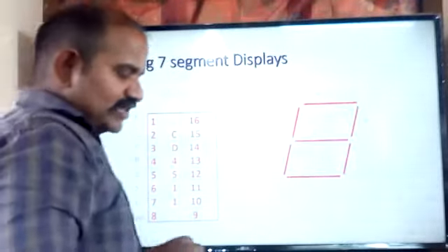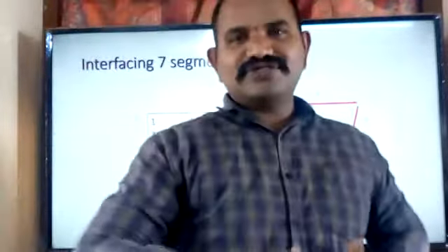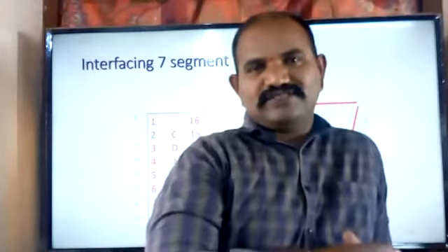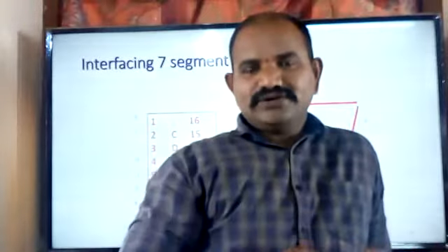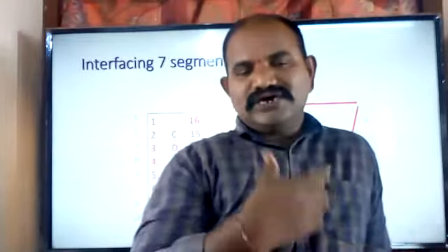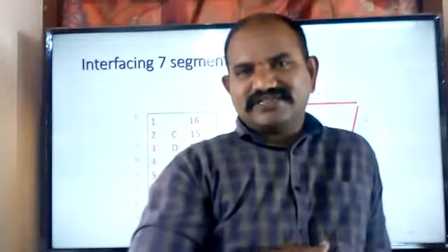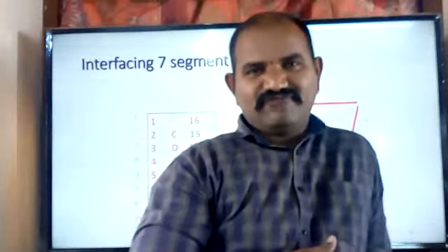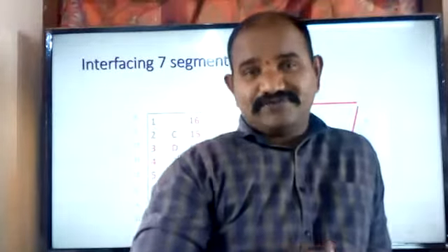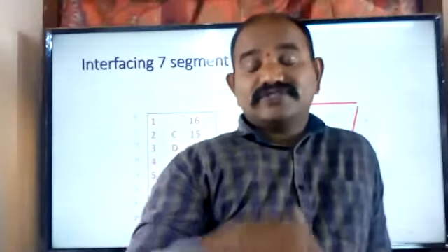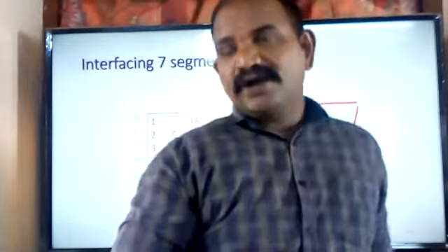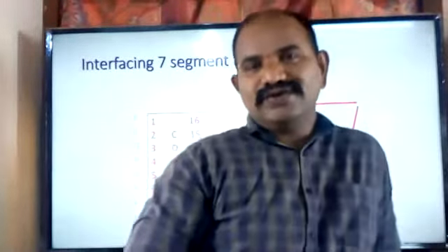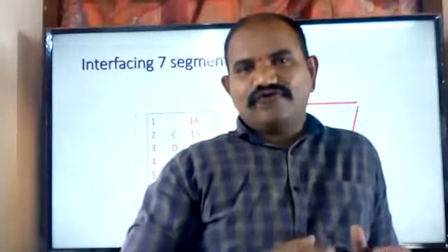In order to display the information from the microcontroller on the 7-segment display, we are supposed to use a mediator to convert the BCD number into the 7-segment format. A BCD number is a 4-bit number. So to convert the 4-bit number into the 7-bit format to display the information on the 7-segment display, we are using a decoder called the CD4511.